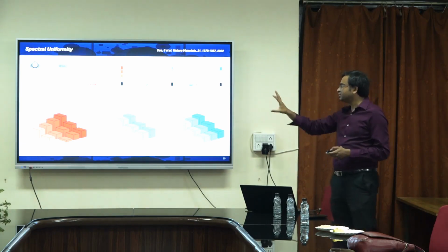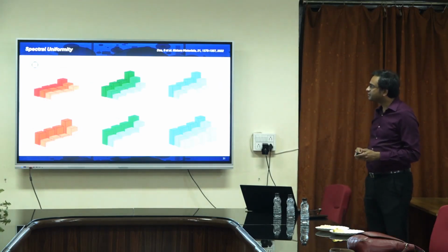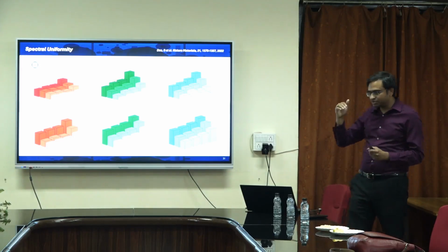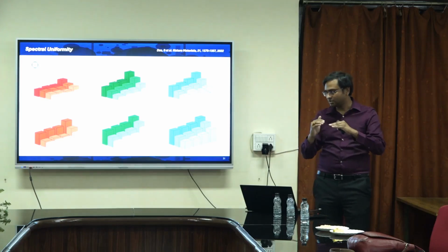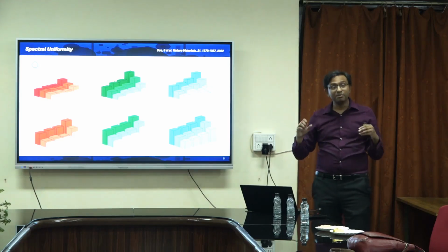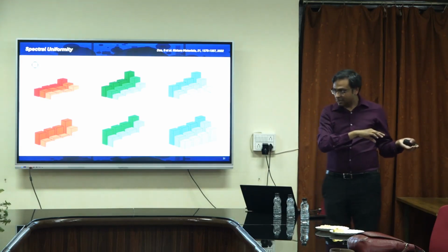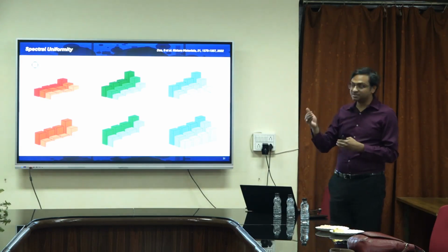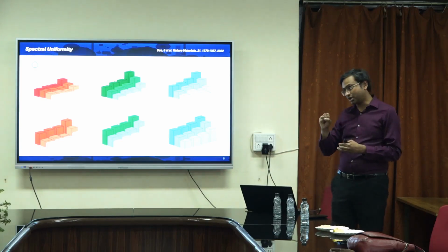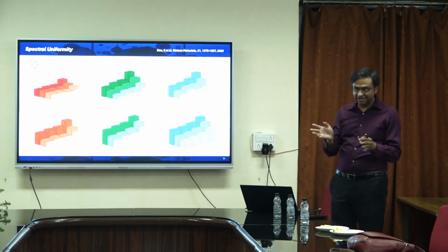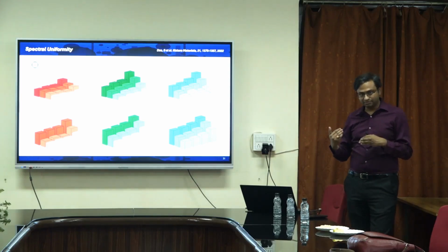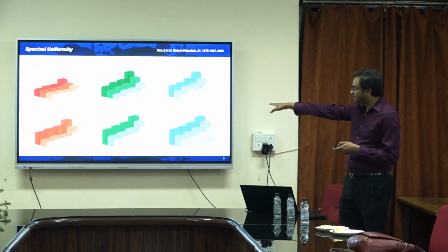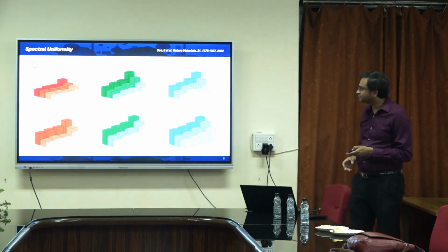I mean, the spectral uniformity part, we don't need to go into too much detail of that. A lot of other characterization where we simply show that by exposing, but this photodetector is also very unique, because if you expose this device longer to the light, you have more photogenerated carriers and more trapping, correct? So you can actually change the memory state by shining the light longer versus shorter. Make sense? That's literally how your vision also works. If you see something for longer versus shorter, that impacts your memory, right? So that's what we can do, and this is kind of a summary of that idea, right?